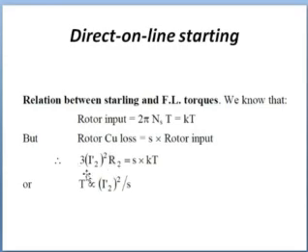So this value is the total power, and the torque will be the power divided by the synchronous speed of the induction motor. From that, we can find the starting torque or full load torque. Torque is proportional to the square of the current. Now for the starting current, this is for direct online starting.